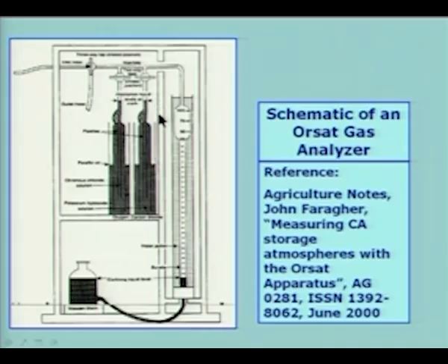Suppose we want to find out how much is the carbon dioxide by volume which is present, we will communicate it with this particular vessel here, and there is of course a mark here. So, the level of this fluid will be up to this mark, and now what we do is we transfer the gas by again raising this and opening this valve, the gas will be sent into this reagent container, where the carbon dioxide will be absorbed by the potassium hydroxide solution. Okay. So, allow enough time for it to come in contact with the potassium hydroxide by arranging such that this level is going to be at this level.